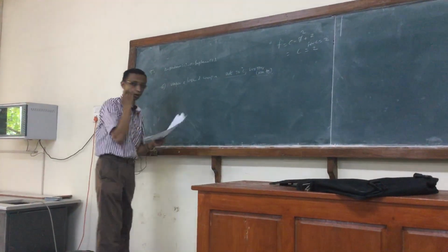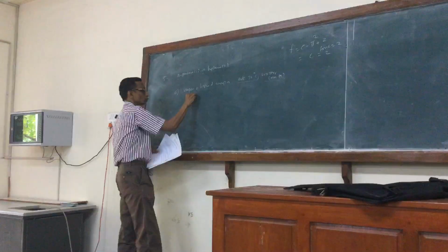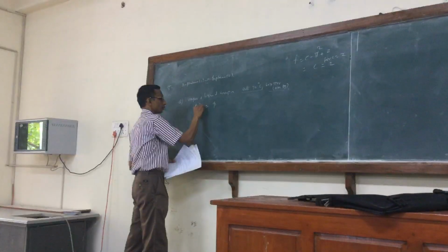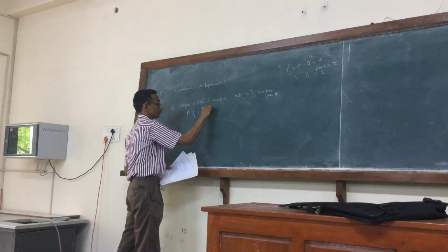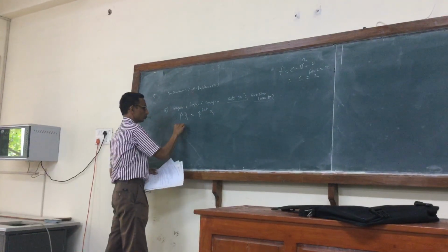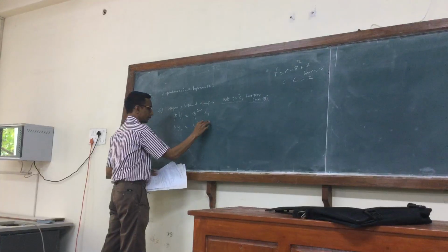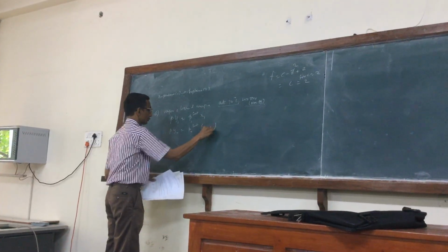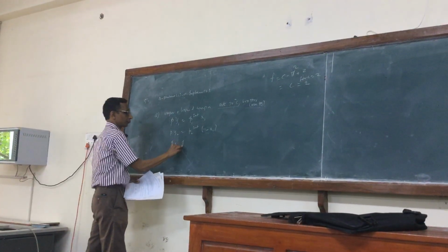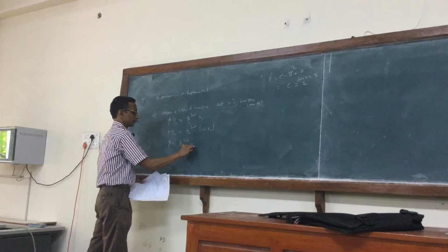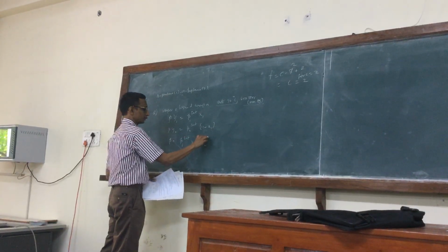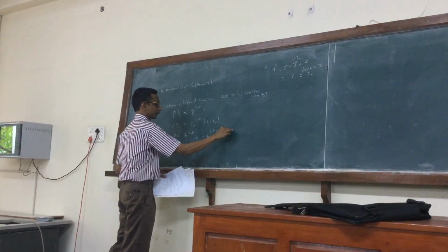5 and 6 using Raoult's law. So very easy to do. y1 is P1 sat x1, y2 is P2 sat x2, and x2 is 1 minus x1. So if I just add them, I get P equals P1 sat x1 plus P2 sat times (1 minus x1).